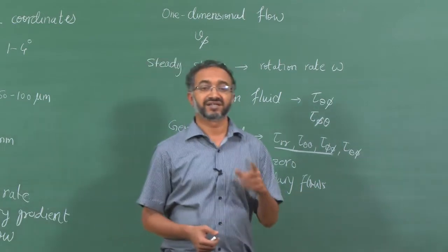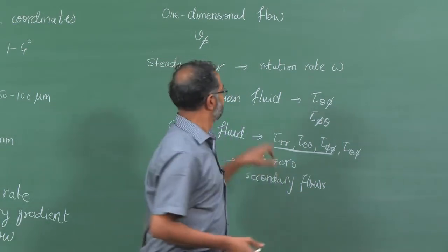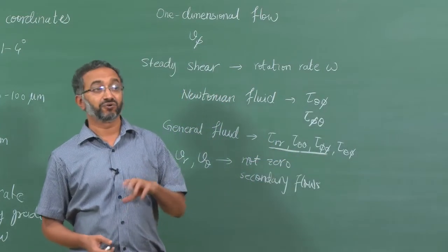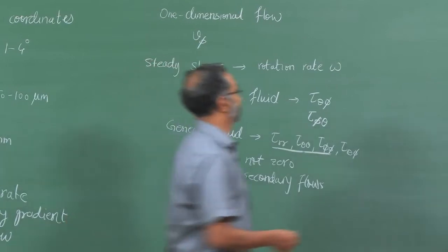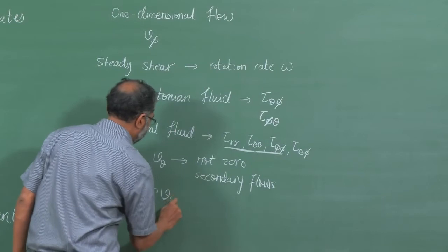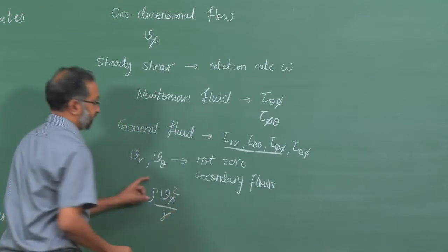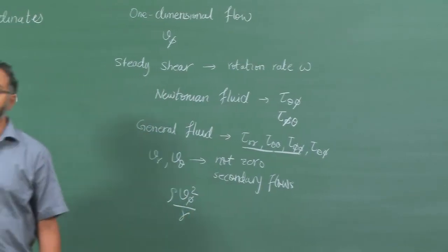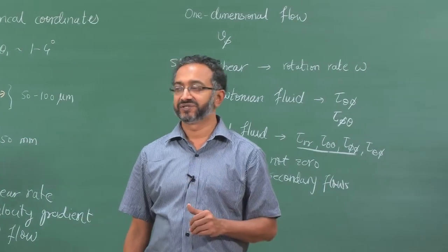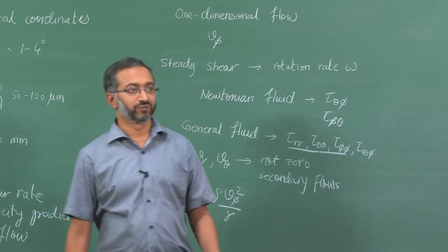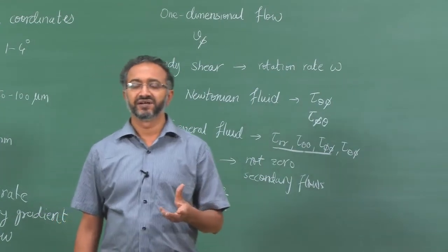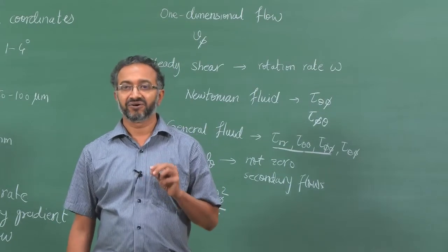What we will see is that in the r and theta directions also these stresses will appear, and similarly centrifugal acceleration, rho V phi squared by r, terms like this, this is nothing but inertia, right. So, this will also appear in the r component of the Navier-Stokes equations or equation of motion. So, clearly whenever there will be inertia or normal stresses, there is a possibility of radial flow.